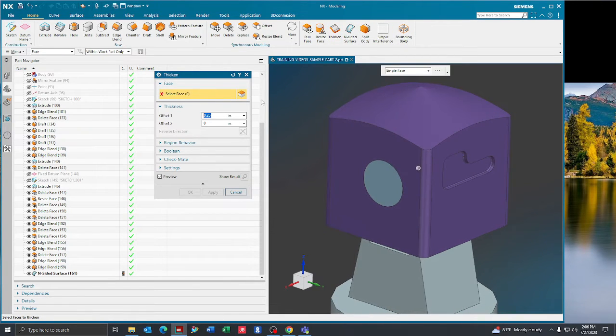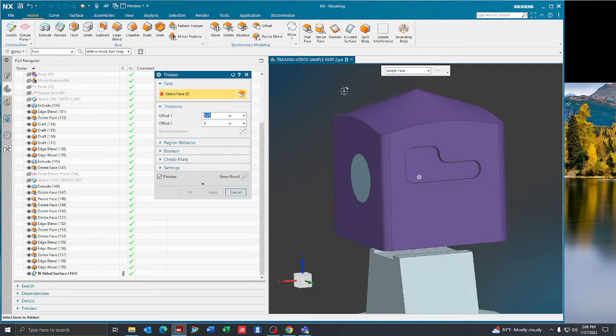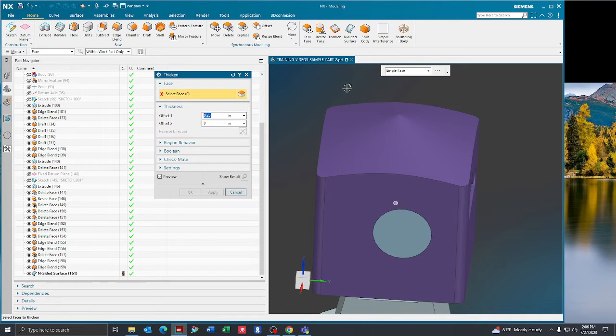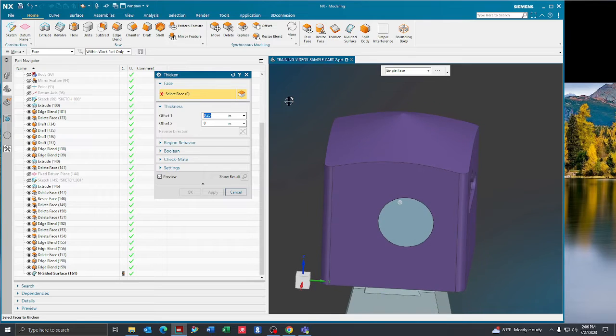And what we're going to do is select this top face. Many times you might have a part that has an odd curvature or just a lot of pockets or various different features that are not just planar or flat. So when it comes to needing to make a fixture for your Op2, it may become difficult or require a lot of modeling. Using the Thicken feature, you can quickly thicken the geometry that's already there on your part and then manipulate that to be used for a fixture.